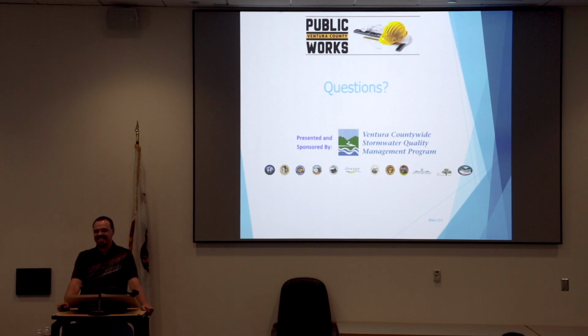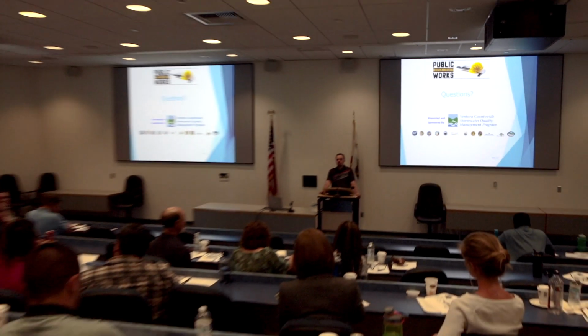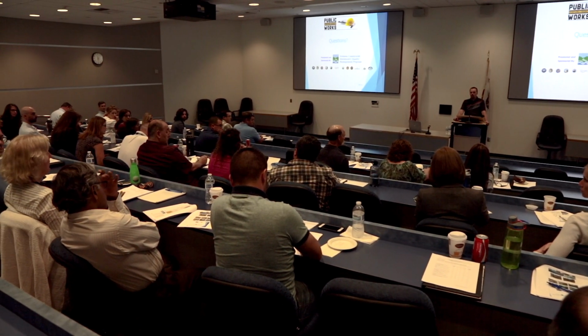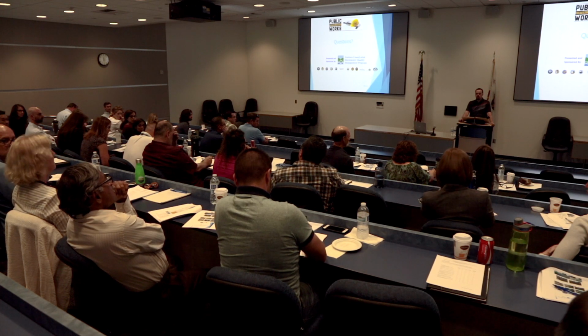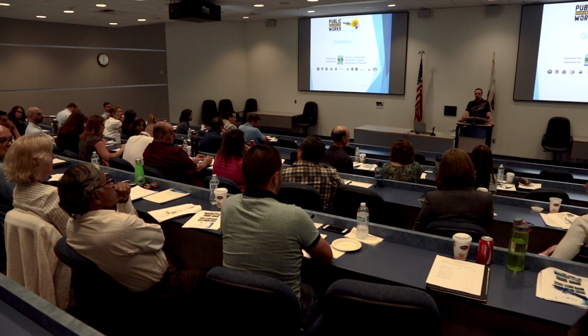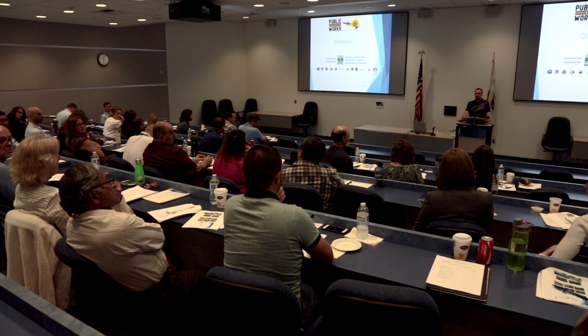Thank you, Troy. My second question is sometimes, say in an industrial or commercial setting, you have a parking lot and using storm chambers is the best way to deal with your retention issues for your stormwater quality. But you also have stormwater quantity issues to take care of because of your pre-developed versus post-development retention issues. Are there any issues with putting it all in the same system? Because you're putting an awful lot more water into it, sometimes depending on your numbers, a 3/4 inch detention or retention situation may be a 2.5 inch retention situation for flood control reasons.